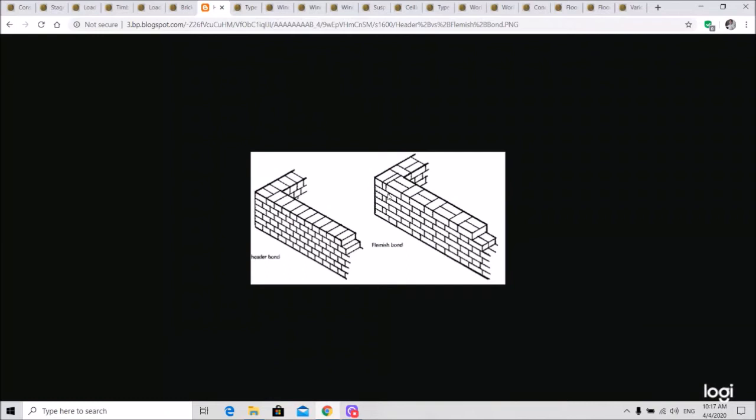Because of these issues, there will be gaps. These gaps they would fill up with half a brick or a quarter of the brick just to fill up this space. In this case, it's maybe half of the brick. So this part is actually called the queen joint. Because you want to have a very nice pattern here, you would leave the side also straight, then you have the joint, the column part, whereby they have to fill up with another half a brick or one brick. So anyway, this is Flemish bond.